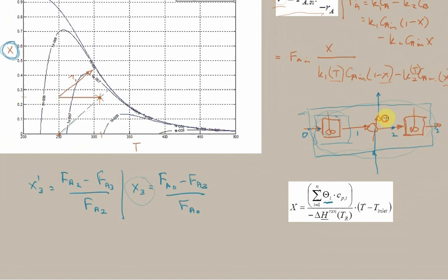We also have to account for this energy that was added. Now, when we were talking about the stepping up procedure using interstage cooling, we were stepping up to that point and then we cooled down the system by changing the temperature in this way, then we stepped up. Then we considered the interstage cooler as being between those two reactors. But now if we are looking at an overall system where, in effect, this heat exchanger is hidden from us and all we can see is heat being removed from the system, then we could regard this heat as being removed from the entry of the reactor in the first place.